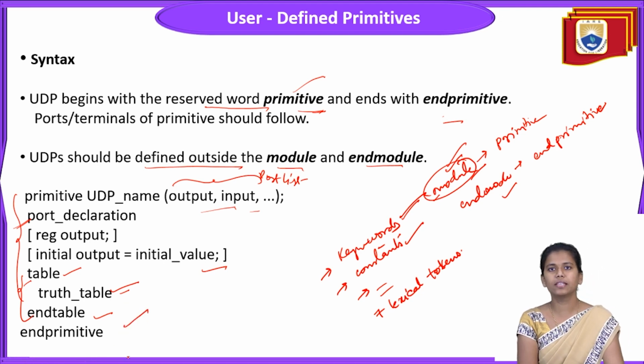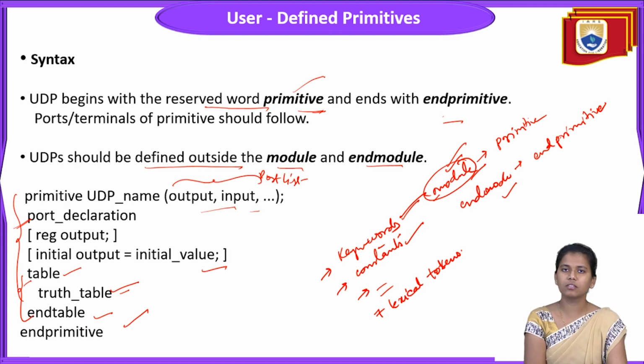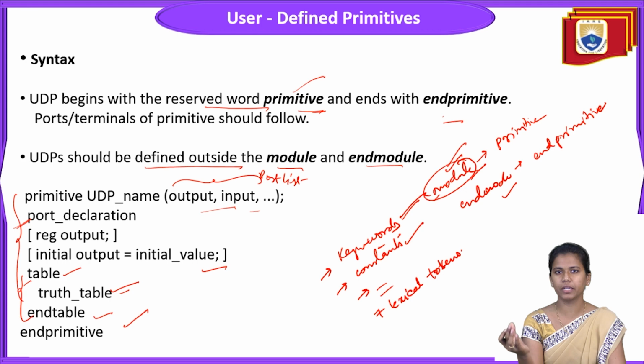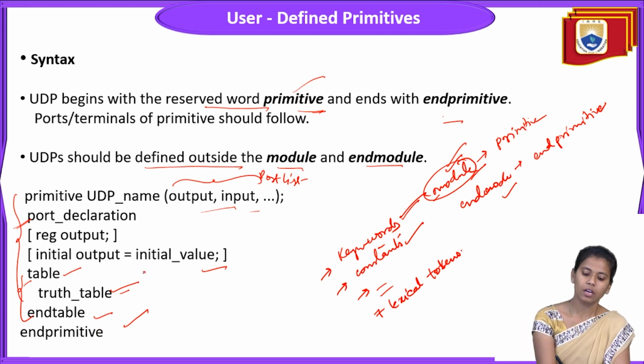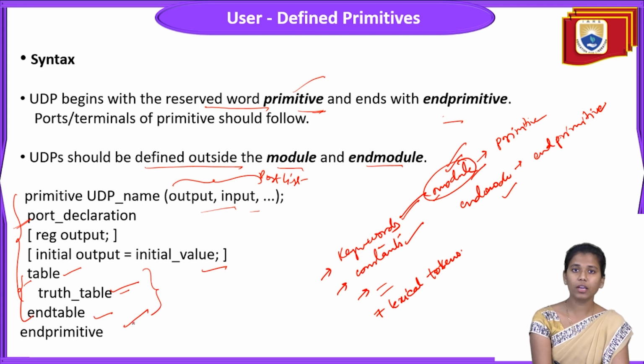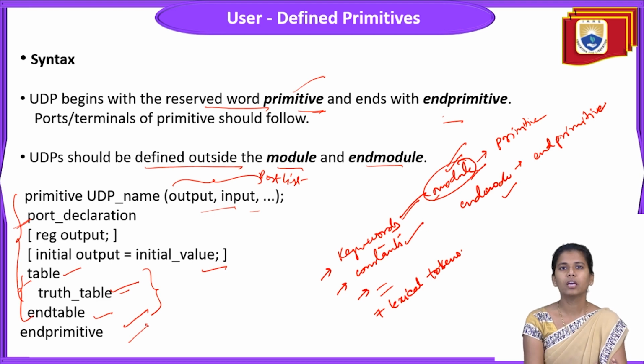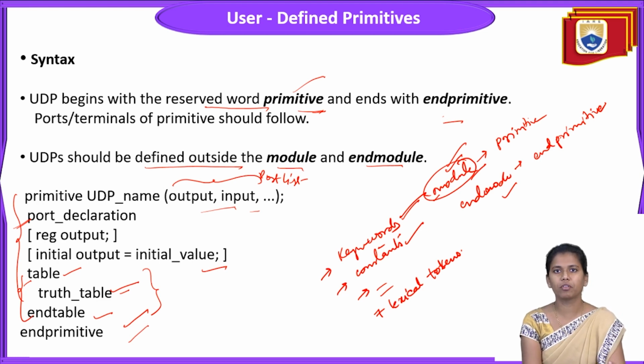Okay, this is very similar to what we have discussed earlier in HDL as Verilog. So primitive UDP is represented with the port list, followed by the declaration of the inputs and the output. And if you have any truth table pertaining to that particular gate, then the table is mentioned over here, and we end the statement with the end primitive. This is how the syntax will be written for all the basic primitives.